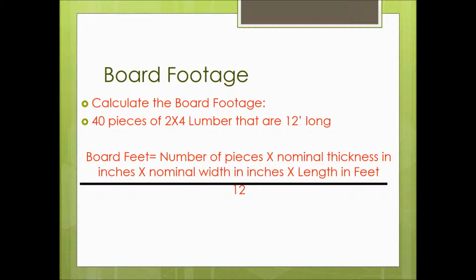So if you're in a cabinet shop and you're ordering maple, oak, walnut, those types of things, then that would be a time when you might need to know the board footage. And when you call those types of places, they may even ask you how many feet. But our little problem here is we've got 40 pieces of 2x4 lumber, and they're 12 feet long.